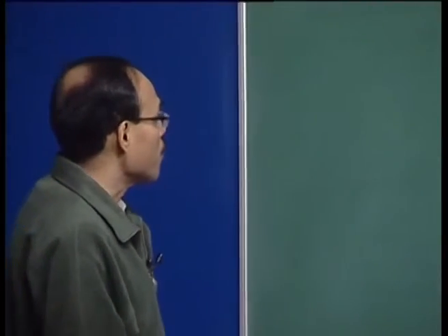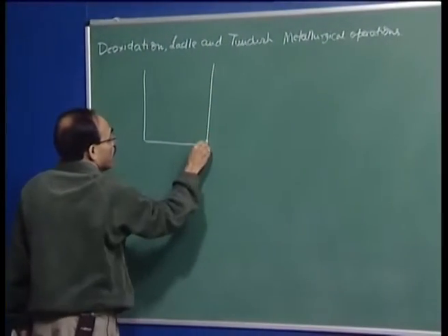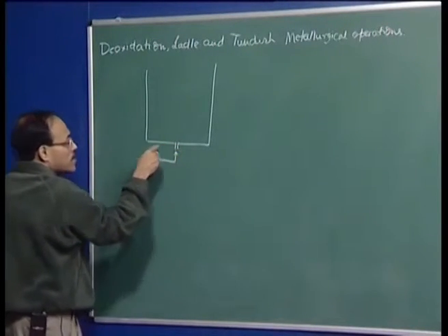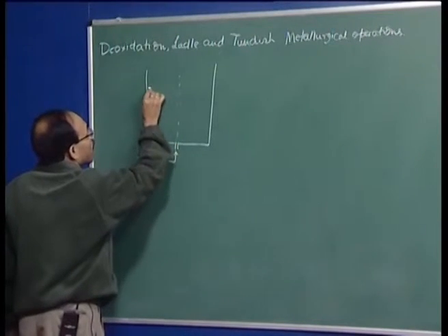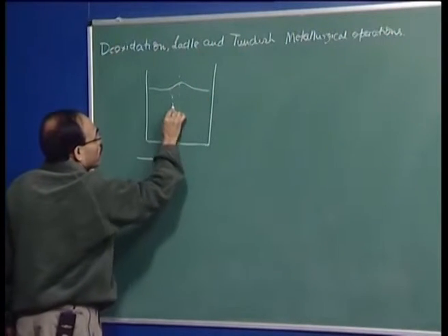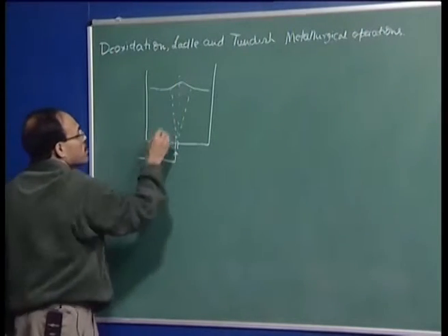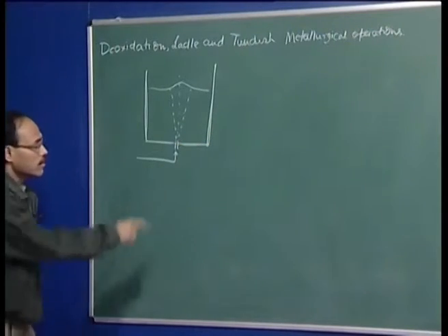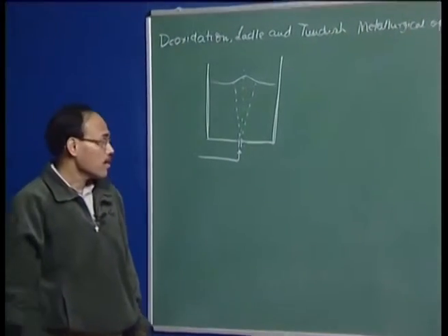Okay, let me now give you a physical picture of gas injection through a schematic of an axisymmetric injection. I have placed the nozzle at the central line, and this is the plume boundary, and this is the axis, and this represents the wall of the ladle. The nozzle is placed at the central line along the axis of symmetry. That is why it is an axisymmetric gas injection.